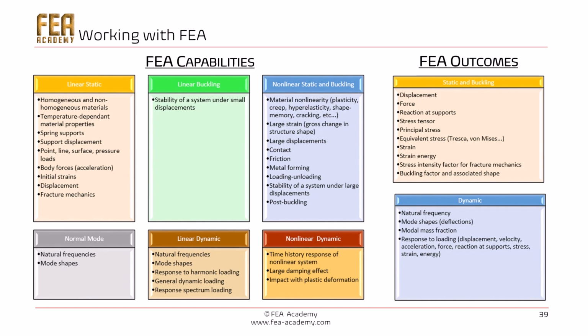The commercial FEA software can solve a variety of single and multi-physics problems, including structural problems and issues of heat transfer, fluid dynamic, acoustic, magnetism, electrical fields, etc. The structural engineers use FEA to ensure that the structure has the necessary strength, stiffness, or life to prevent failure due to an excess of stress, resonance, buckling, or detrimental deformation that may compromise the structural integrity.